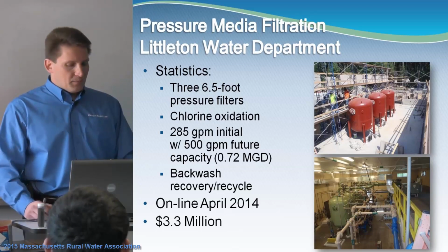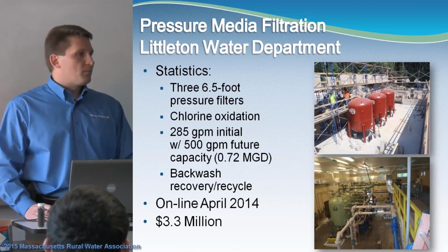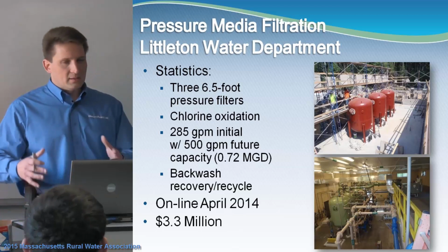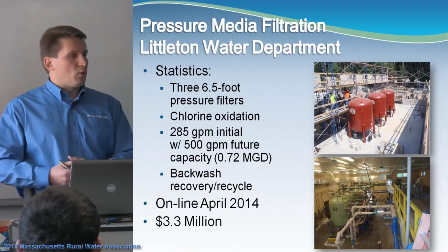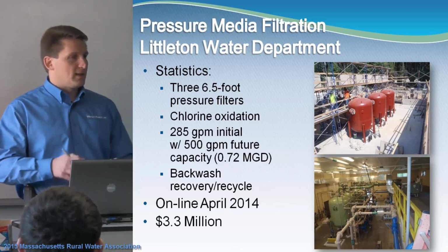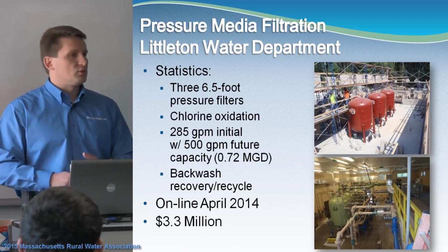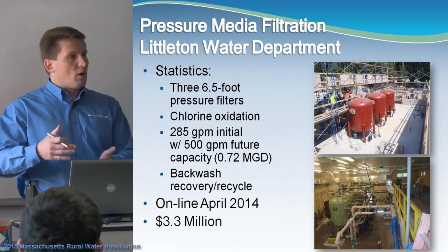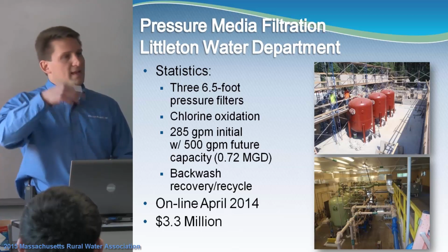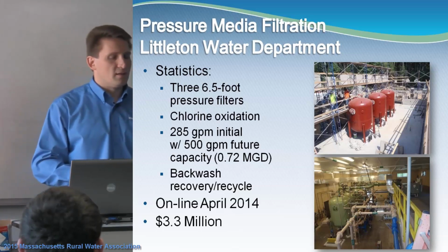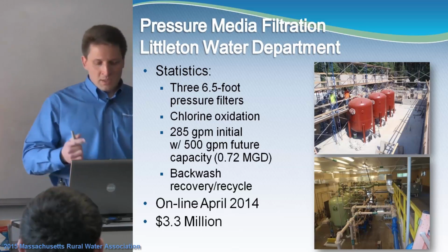They also had a backwash recovery and recycle process to increase the throughput of the facility. Basically, every so many hours you need to backwash your filters, and rather than taking that dirty backwash water and just letting it go into the ground or some sort of infiltration lagoon, we designed a couple of tanks to hold that water and allow it to settle, and then that clarified water was recycled to the head of the plant to increase the production through the facility.